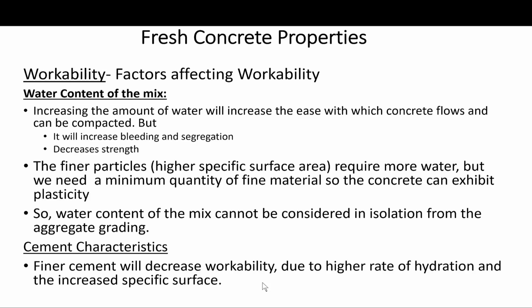So how does the water content of the mix affect workability? This is the single most important factor governing workability of concrete. Increasing the amount of water will increase the ease with which concrete flows and can be compacted.